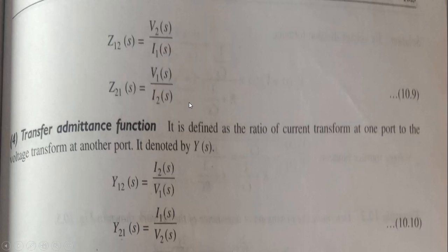Similarly, if you're talking about the transfer function of the admittance, that is nothing but Y. Again you need to take care about the terminals, that is 1 and 2, and 2 and 1. So here again it is the vice versa case with the impedances. Whatever you are taking here as Z12, V2 divided by I1, here it will be the opposite: instead of voltage here will be the current, and instead of current here is the voltage. Only the notation will be the same, that is 2 and 1 will be the same, but instead of voltage, current will be there, and instead of current, voltage will be there. In this way you can find it in the frequency domain.